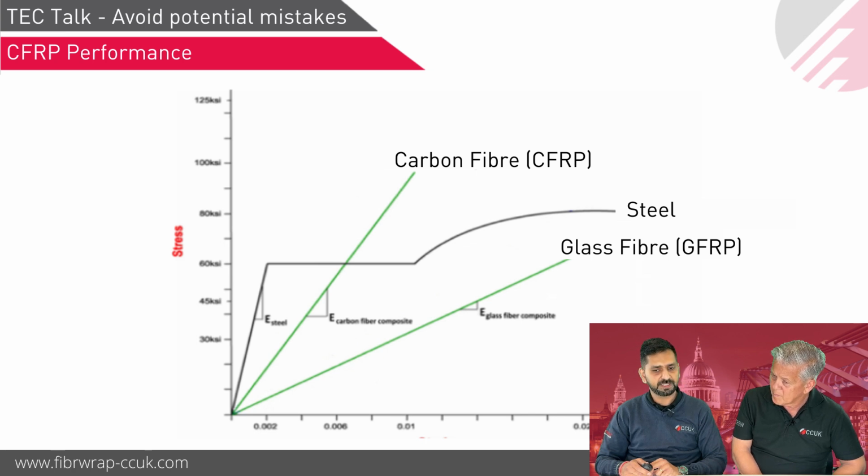That will give them the tensile stress or design tensile stress for the FRP, and that stress should be used to calculate the area of FRP required for a particular force. So again, I'd say it's a strain limit design. You should always design it based on the strain limitation depending on the guideline you're using, and should never just use the tensile stresses given on the data sheet, because those are ultimate tensile stresses.